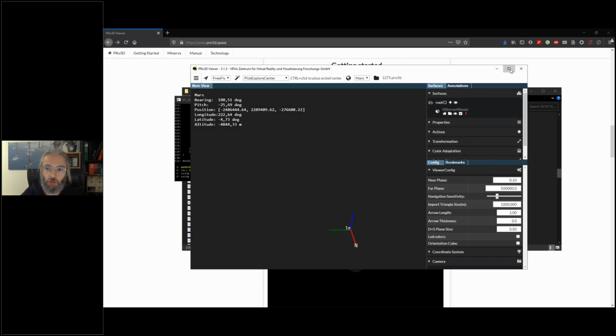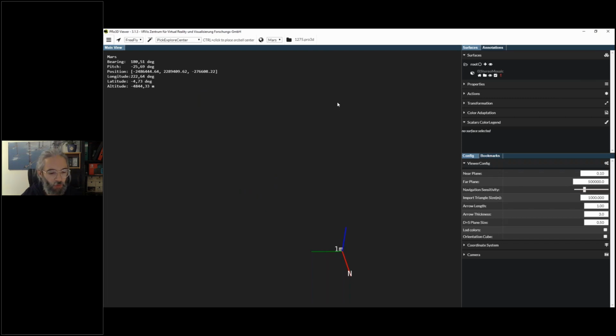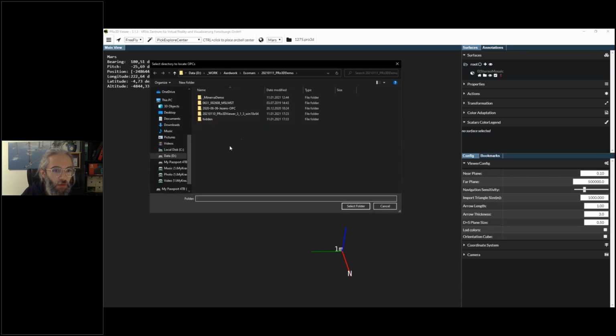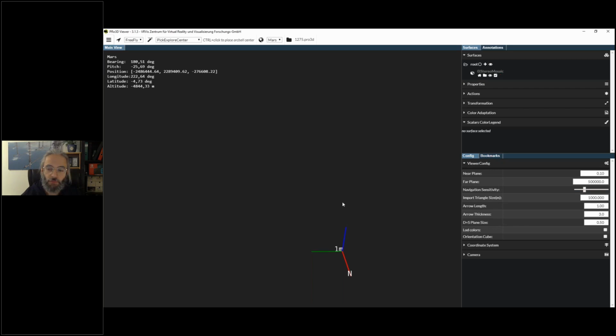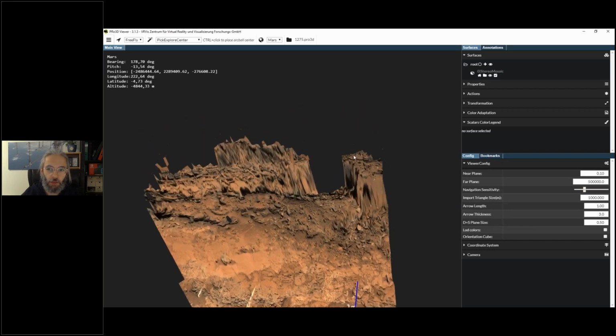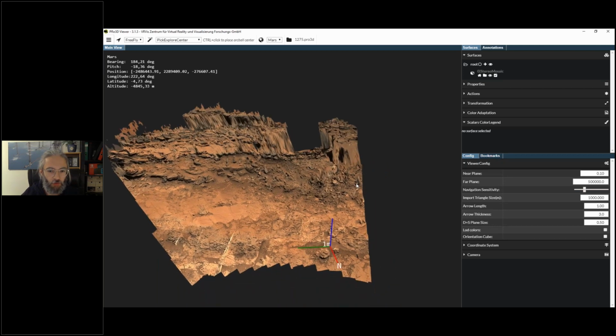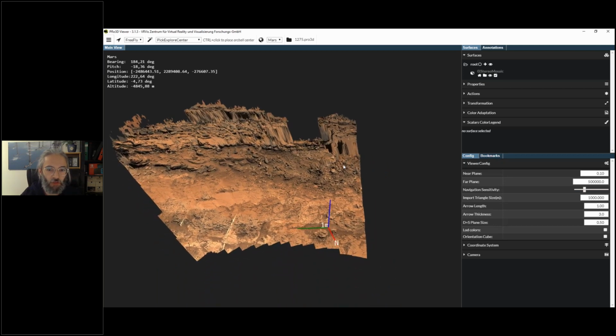But we have a little problem here. We use absolute paths, so you can store your OPCs anywhere or also in a central location. But when this little exclamation mark comes up, PRo3D cannot find your surface. But this is quite easy to resolve. Similar to, I think, how Adobe products do this, similar to Lightroom, you can tell PRo3D where to look for your surface. So we look in this hidden folder, and there it is back again. So this is quite useful when you're collaborating with other people or if you're changing machines a lot.